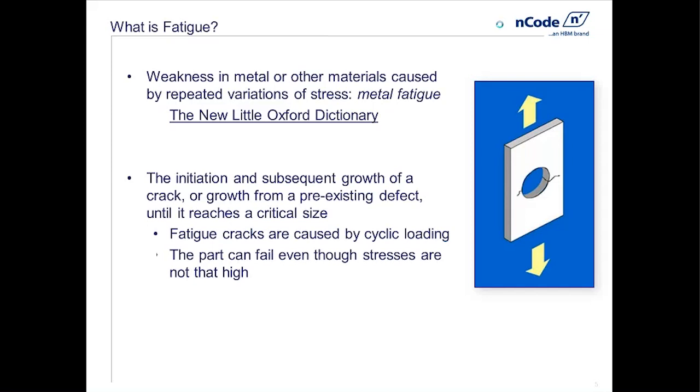The challenge in fatigue is that parts can fail even though stresses aren't that high. This can surprise people sometimes. When we say we designed this thing that it would never fail, in other words, the part won't yield in some static way, it won't fail. But even if the stresses are smaller than that, over time enough cycles can build up to cause a crack.